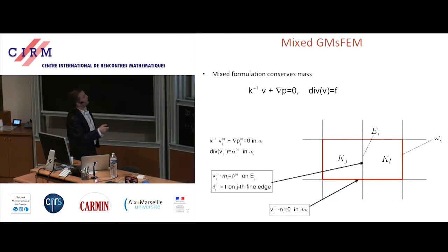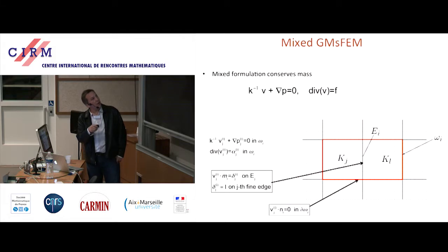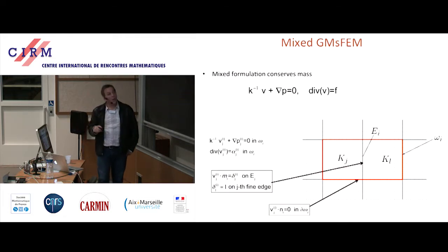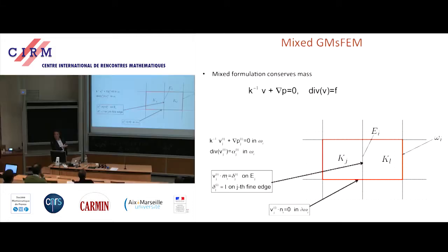So the way we build mixed finite elements, I'm showing the slides because I want to describe the method a little bit. So what we end up doing is, again, we have to solve this problem where this coefficient may have significant variance over the domain. And we have the coarse problem in which, for each of these segments, we impose a flux of 1, constant pressure on both sides, and solve each of these problems to capture snapshots.